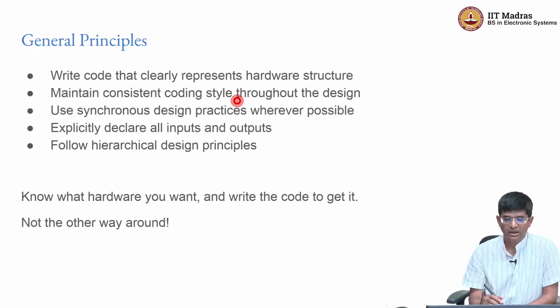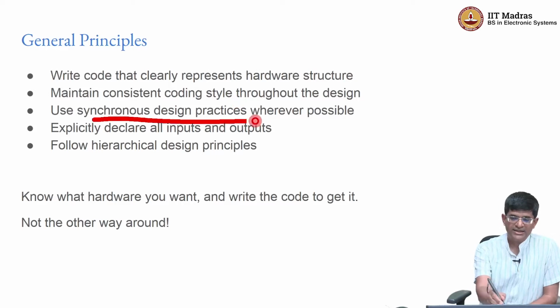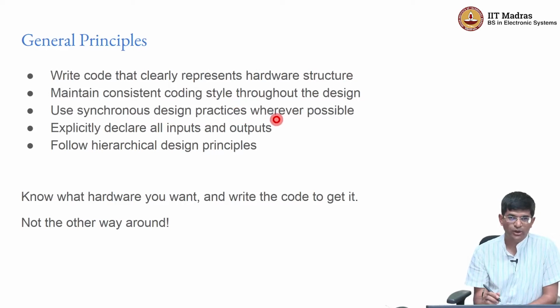That's all. Use synchronous design practices. This is not just to do with coding style. Synchronous design practices means the actual proper use of a clock and keeping that clean separation between the combinational update and the sequential logic, right? The combinational computation and the sequential update of the logic. By keeping that clear, it means that you have good synchronous design and it will all synthesize cleanly into a set of registers and computations.